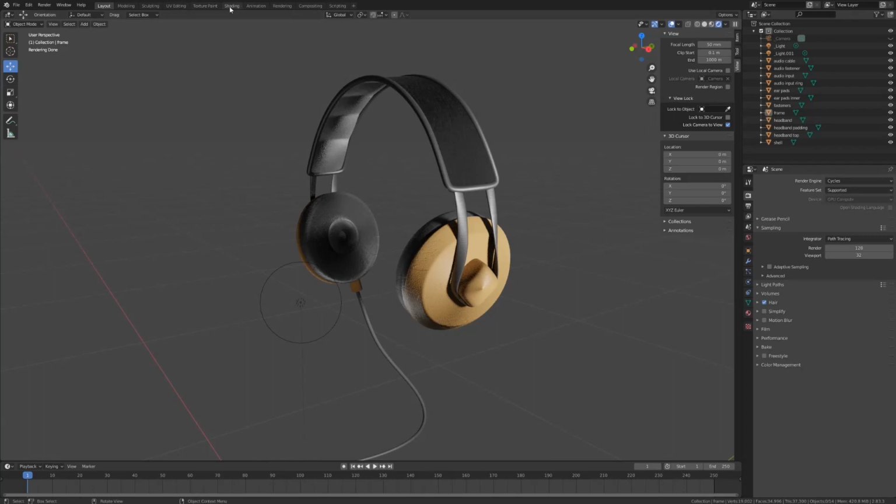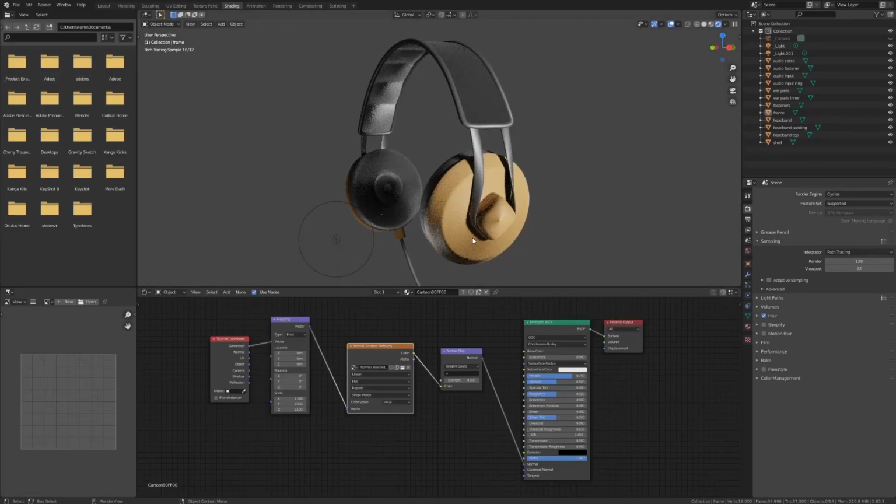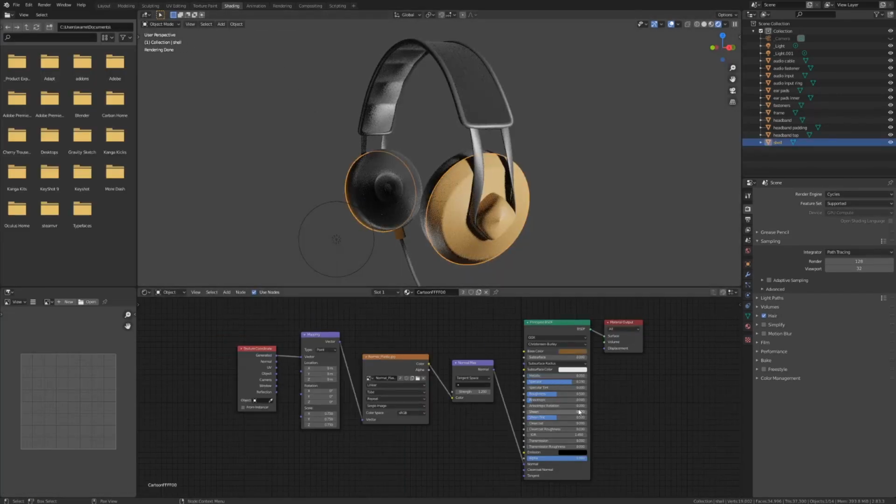Now, if we go to shading, we can see how we achieve these materials with these graphs. If I click on this icon, I can apply a material with this menu without having to completely recreate all of these new nodes. So for example, these two share the same material, and I did that with this interface. Now, I'll bring you through all of these parts, and for example, with this, there's a normal map, and I've linked all of these normal maps in the description.